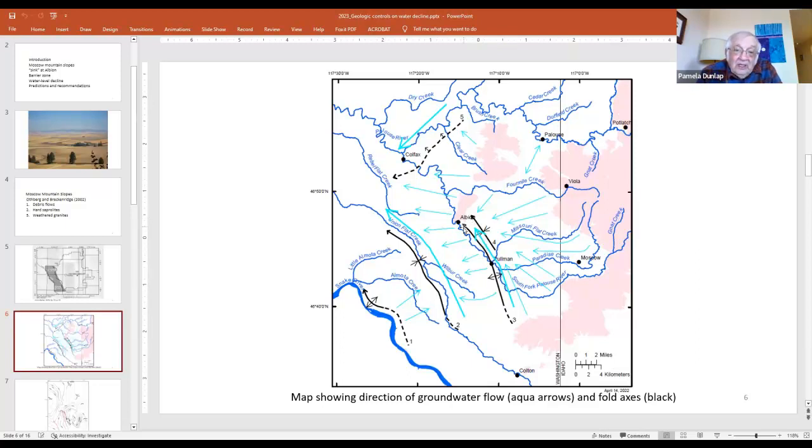And then the intraflow contacts in Albion are lower than the intraflow contacts across the central part of the basin. In the central part of the basin, the Moscow-Pullman basin, the contacts are horizontal, but I believe the structures in this little area around Albion, about a 9 square mile area, where the folds are plunging, meaning that the slope of the fold is increasing, cause the intraflow contacts to drop into the Albion area. So I think we presented that the folds and this sink, as I call it, up here in Albion, is controlling the way the groundwater is moving and trying to get out of the Moscow-Pullman area out into the west.